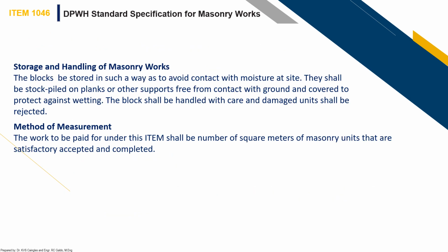And also natin provision on how to properly store and handle our masonry works. Okay, so the blocks or masonry units. Okay, so the blocks are to be stored in such a way as to avoid contact with moisture at site. Okay, they shall be stockpiled on planks or other supports free from contact with ground and covered to protect against wetting. The blocks shall be handled with care and damaged units shall be, of course, rejected. Okay, and the method of measurement na yun, per square meter.